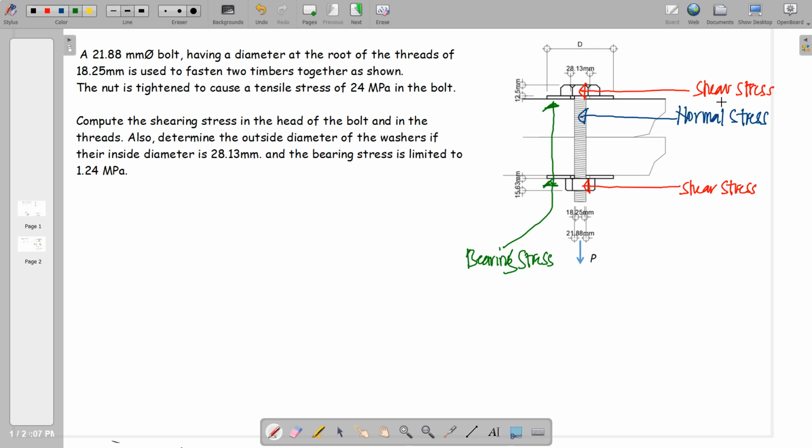And then for the shear stress, of course, the shear stress is a cutting force which is tangential to the section. So if we take a look at the head of the bolt, if this is in stretch mode, say this is the head, there will be shear forces surrounding the perimeter wherein the shaft is attached to the head because it is actually pulling this, causing a hole in it.